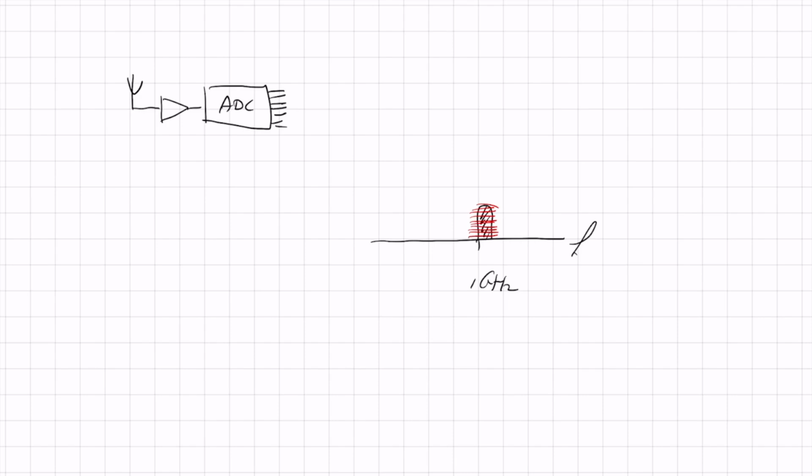Of course, if the input signal is 1 gigahertz, the sample frequency should be bigger than 2 gigahertz, else I don't satisfy the Nyquist criterion. So then you can say, well, maybe 6 bits is enough, 2 gigasample, well, that still sounds feasible.